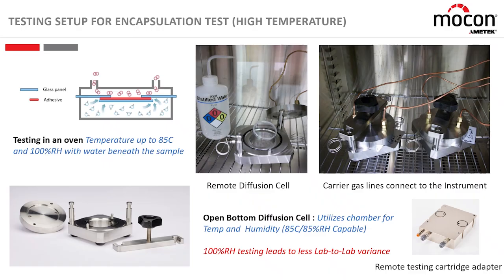I rented a chamber here once for a client where they wanted it done. They had to have the test. Brought in someone. They said, we really can't calibrate it at that condition. We calibrate the humidity probe at a lower temperature, and then it's assumed it's all working right. And anecdotally, I think when they get one and they get their second one, especially if they're doing other tests like maybe a calcium test or other tests for barrier, and they realize the two chambers don't produce the exact same results, then they realize, guess what? There is some variance of that condition.